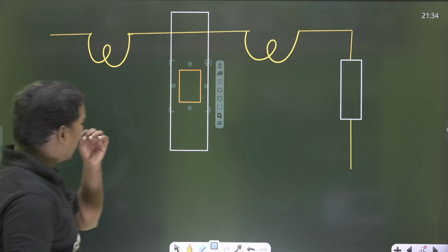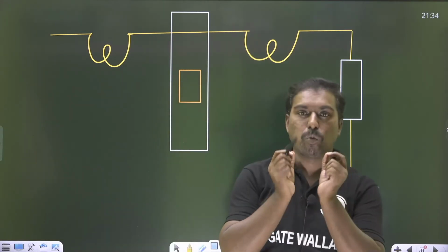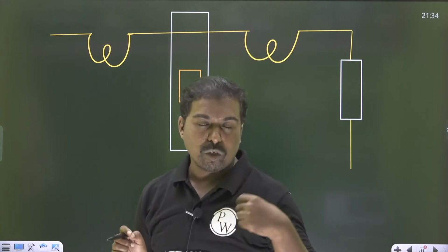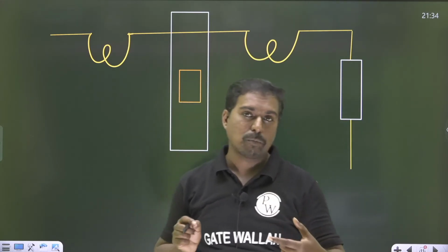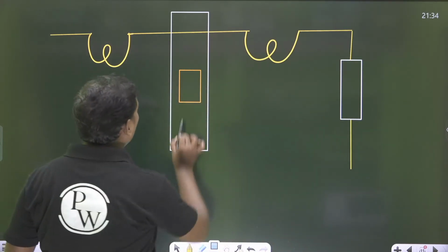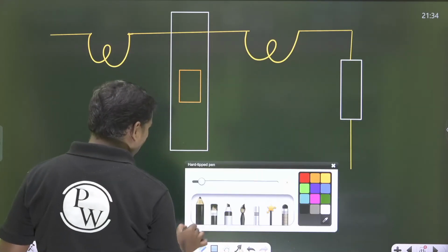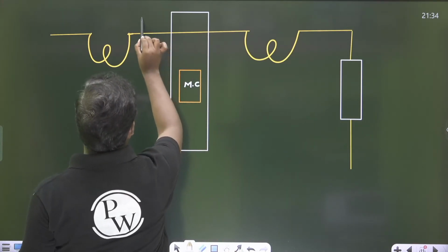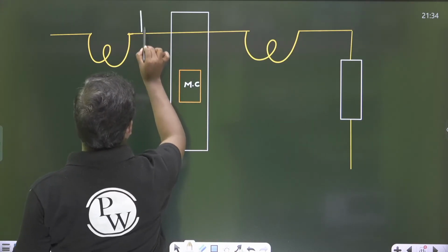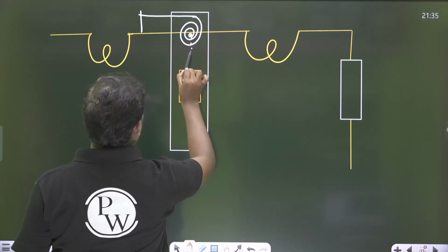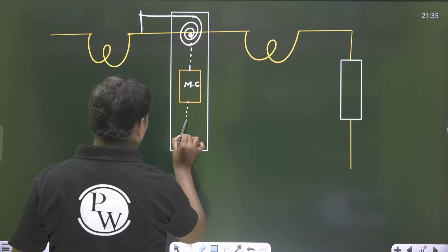A small adjustment we have to do to get the voltage, because the deflection torque is proportional to average power, that is, theta is proportional to average power. So how to get this V? This is a moving coil, my dear. Here we are having two springs, one spring here and this is another spring.